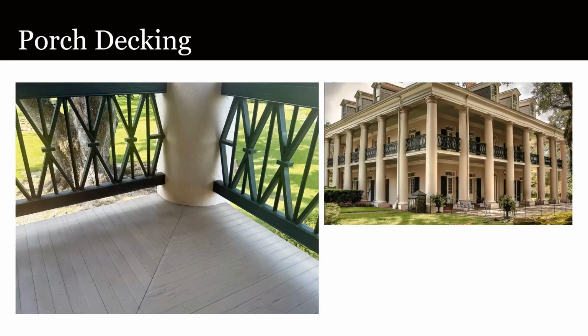This second-story porch is a pre-finished material that has held up well for the several years it has been in place at this Southern House Museum. What is significant about this installation is that the product chosen was acceptable to install directly atop a waterproof membrane, making the deck effectively a roof and protecting the ceiling below, as well as the structural framing itself, from water and its effects. Other tongue and groove products can also be installed over a membrane, but require intervening sleepers as part of the assembly to facilitate drainage.